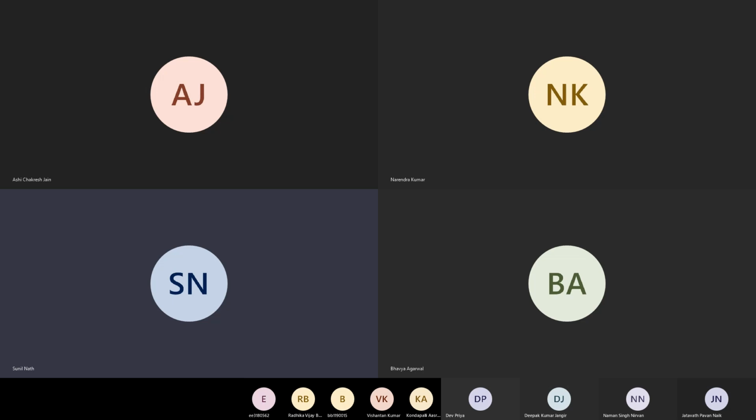That has to equal the crystals, because that's pure potassium chromate, C, plus the mother liquor S times 0.3636, because that's the composition of potassium chromate in the mother liquor. So you get the other equation from an overall balance on the potassium chromate: 1/3 times 4,500 equals C, the crystals, plus 0.3636 times S. And that's why C will be less than 1,500.